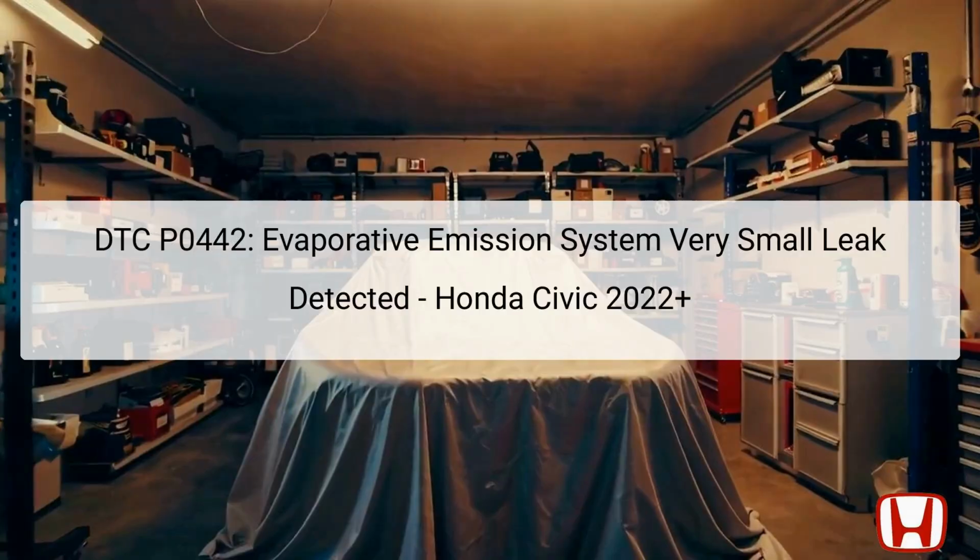Understanding the P0442 Diagnostic Trouble Code, DTC, for the 2022 Plus Honda Civic is crucial for effective troubleshooting. This code indicates that the evaporative emission system has detected a very small leak. The EVAP system is designed to control fuel vapor emissions from the fuel tank, ensuring that harmful gases do not escape into the atmosphere. The main components involved in this system include the fuel tank, the EVAP canister, purge valve, vent shut valve, and various hoses.